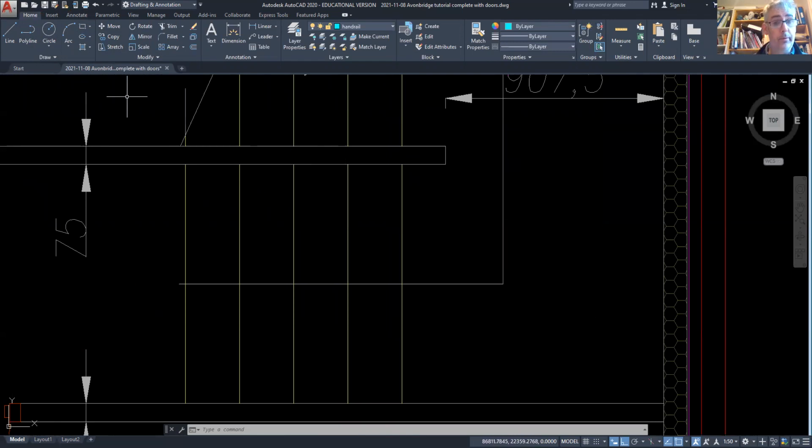So I'm just going to draw a line from here because the handrail will extend beyond the bottom stair slightly up to here, and you'll see I've made that overlap the wall. I'm just going to get the middle grip and push it out the way by 50.